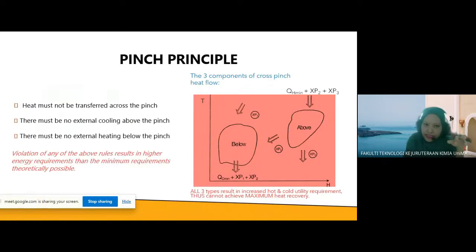So this is the principle we discussed earlier. Heat must not be transferred across the pinch. There must be no external cooling above the pinch and no external heating below the pinch.